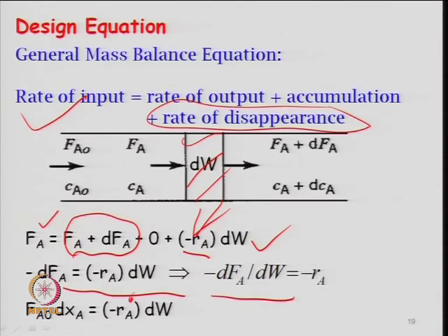So, one can very easily define this density of the catalyst, as I discussed earlier, based on the bed volume, when you are calculating the mass of the catalyst in a bed. The volume will increase because there are voids between the particles, that is the bed void fraction I am talking about. So, 1 minus epsilon b, where epsilon b is the void fraction of the bed, is the solid fraction, that is the catalyst which is present. If I define my density based on the mass of the catalyst divided by the volume of the bed, this is the bulk density of the catalyst.